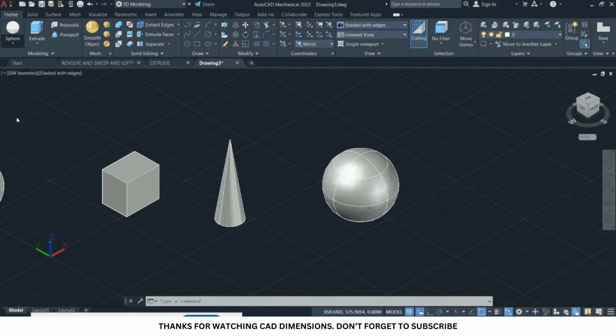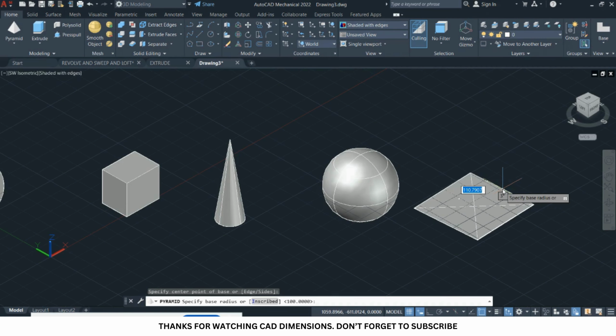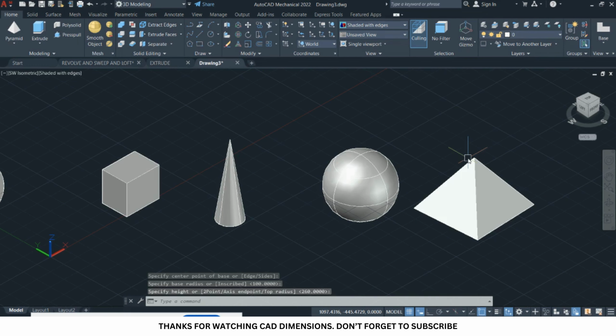Then we have the pyramid. For the pyramid, it's the same thing. You specify the base point and then you specify the end point. Okay, you can change the direction of the end point and all of that. Now, with the pyramid, you can also change how the pyramid is drawn, either with respect to inscribe or circumscribe.